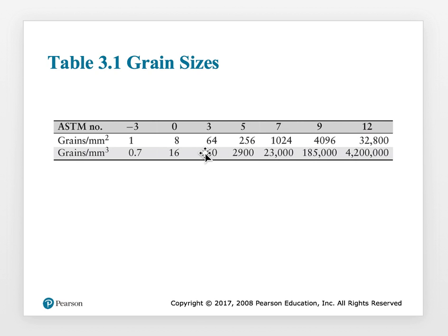So suppose you did cold rolling, which means that all the grains are oriented in one direction, but you have increased the number of grains tremendously. Okay, so if you have done cold rolling, that cold roll sheet will have much higher strength compared to an as prepared block of atoms.